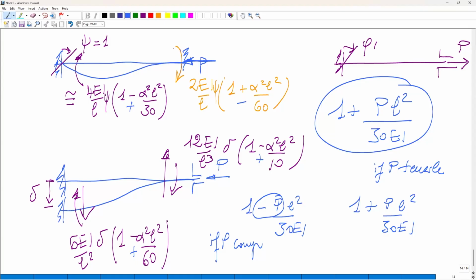So that number here, 4EJ and so on, is the rotational stiffness. You see that if our axial force is compressive, this is a minus: the compressive axial force is reducing the stiffness. The tensile axial force is increasing the stiffness. And it's always like this, except that this is an indirect stiffness, so if you decrease in one place, you have the opposite effect on the other.